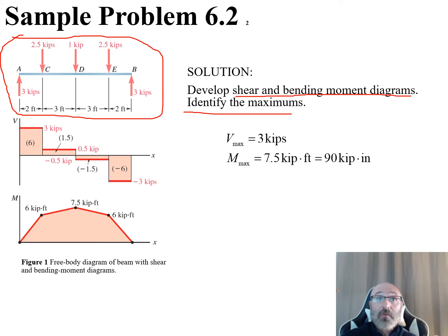So now we know for the simply supported beam, we can divide that, and we have a reaction force at each end that is equal to each other and sums to the total at the top. So if this is 6, this is going to be 3 and 3. So 3 at A and 3 at B. And we now know the difference between all of these. So the next thing we want to do is figure out our shear at each of these.